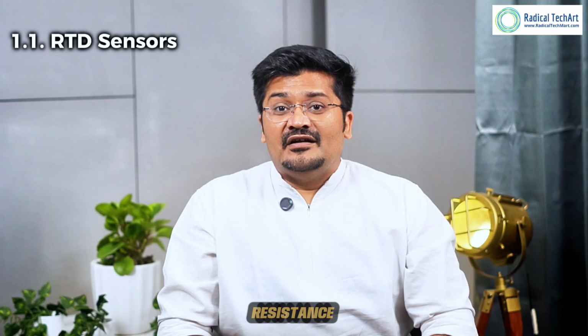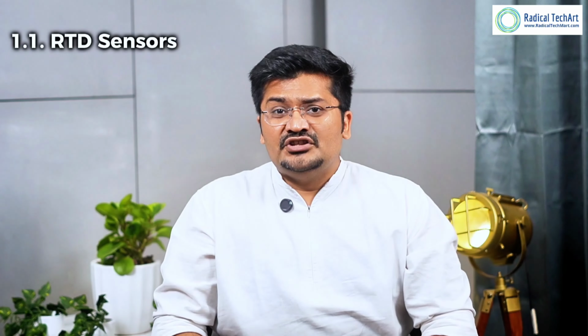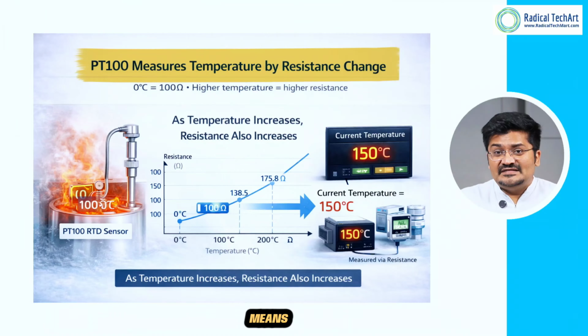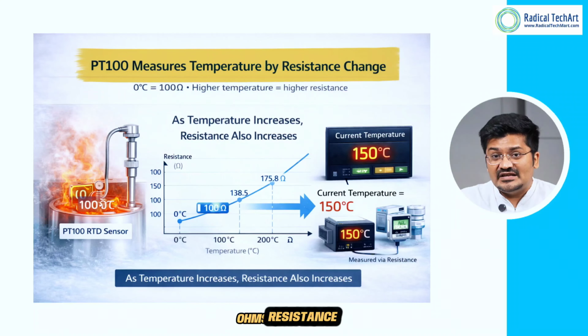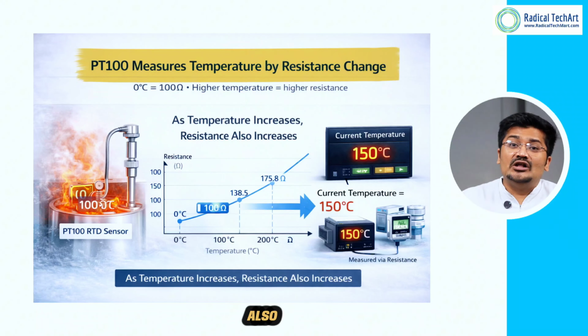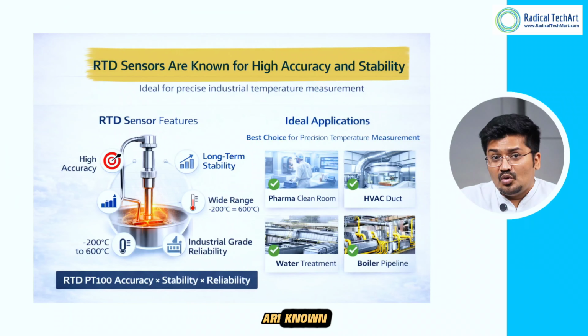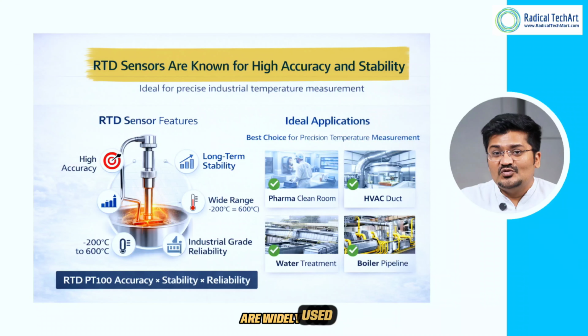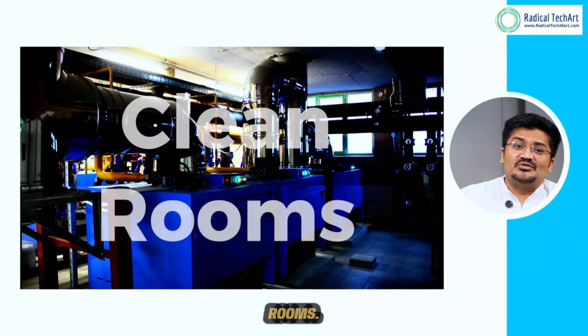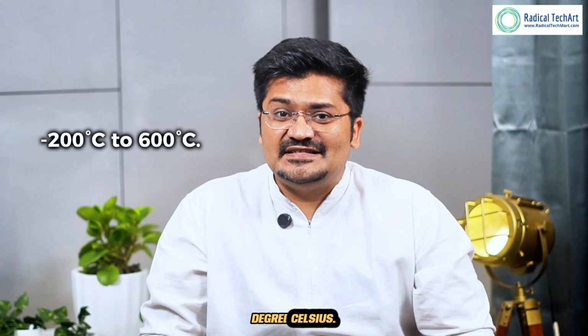RTD stands for resistance temperature detector. The most common RTD used in industry is PT100. PT100 means that the sensor has 100 ohms resistance at 0 degrees Celsius. As temperature increases, the resistance also increases. RTD sensors are known for high accuracy and stability. That is why RTDs are widely used in pharmaceutical industries, food industries, HVAC systems, and clean rooms. Typical temperature range of an RTD sensor is around -200 degrees Celsius to 600 degrees Celsius.